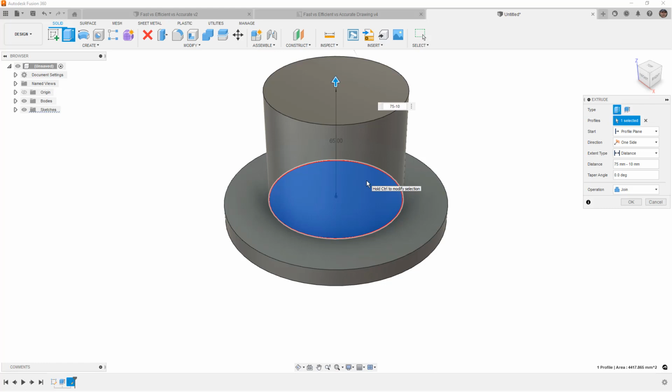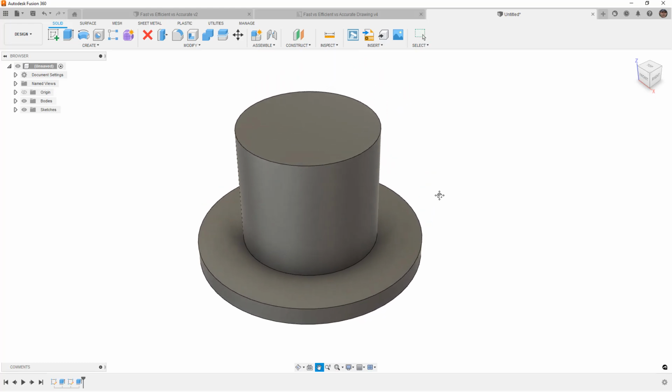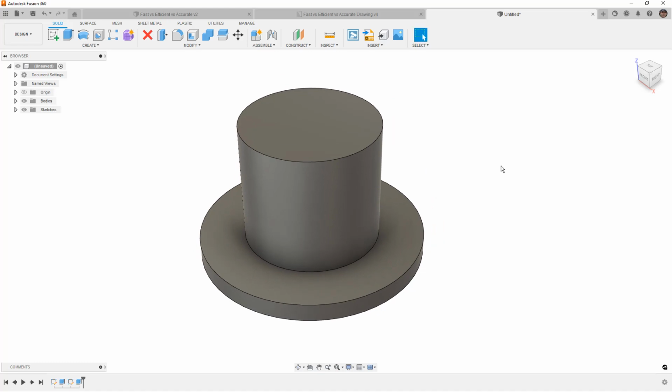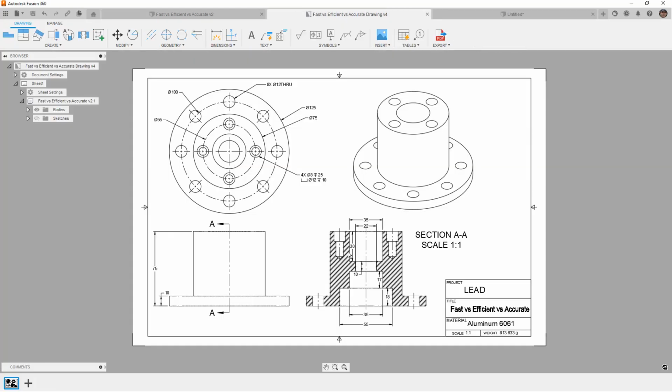Now, in reality, to maintain sort of accuracy with the detailed drawing, what I would want to do is start from an object, select the bottom of my part, and then enter that 75 millimeters. But in this case, we're just going to accept 65 or 75 minus 10, which gives us 65. So once again, it's really quick if we just simply select a face and hit C on the keyboard. The next bit of this detailed drawing on the inside would really be best served as doing a sketch and creating a revolved cut. And there are ways that we can speed through that a little bit.